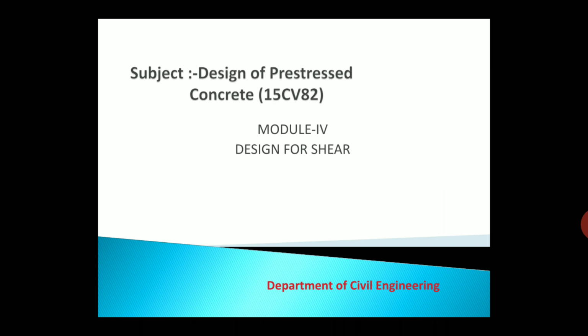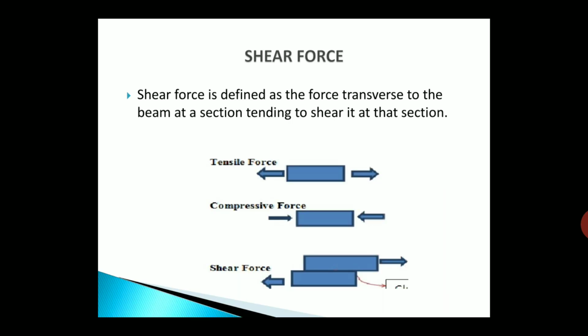In today's lecture, we will be starting with module 4, which is design for shear. In the previous module, we went through the design for flexure, and now in this module we will be studying design of shear. Let us start with the definition of shear force. Shear force is defined as the force transverse to the beam at a section tending to shear at that section.